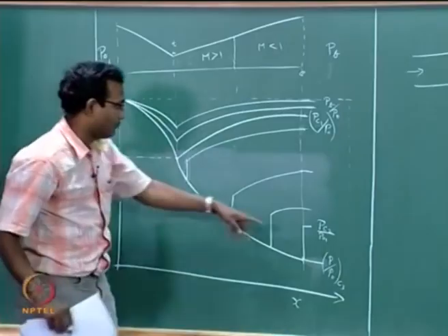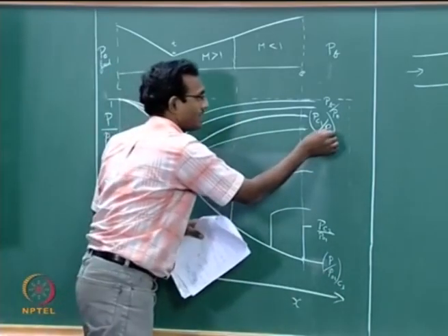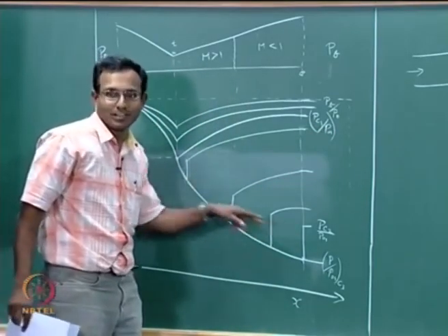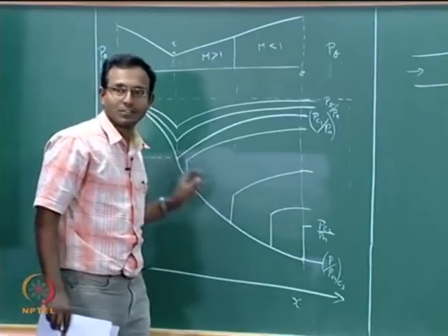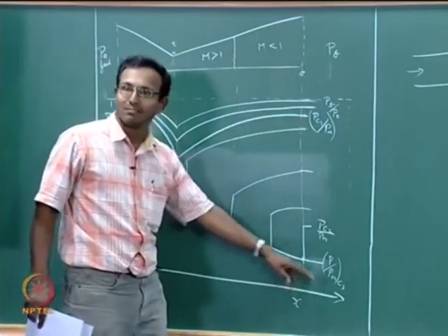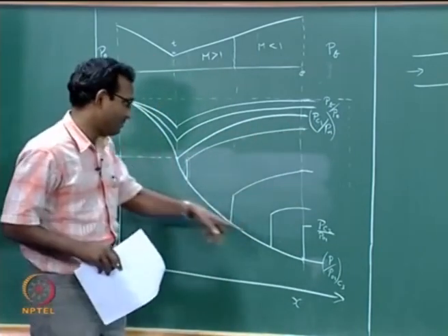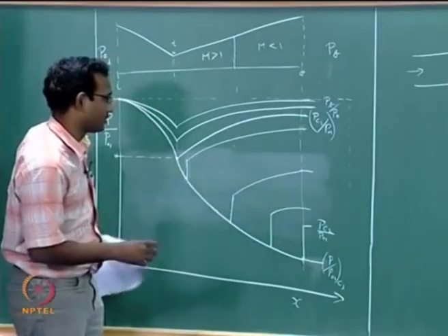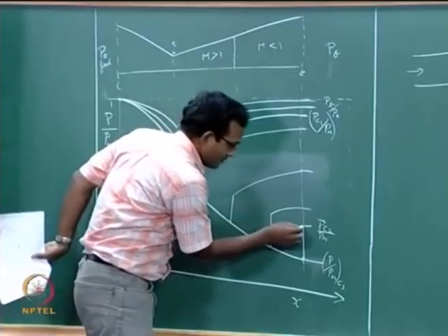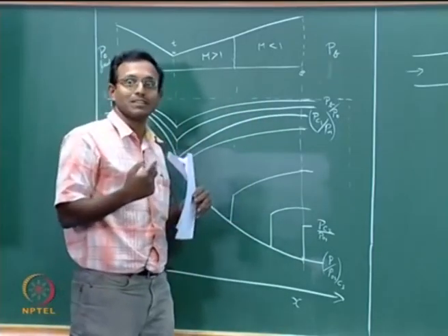Okay. I am again being very careful in marking P naught 1 always. That is our normalizing factor. There could be a P naught 2 in case of non-isentropic problems where there is a shock sitting inside my divergent duct. It does not matter for P critical 1 or 3, but anyway just for consistency I put P01 everywhere. It matters mainly for the other cases where there is a shock sitting. So if this is the problem, now there is a shock at the exit, and immediately after the shock the flow is meeting the pressure that is outside.